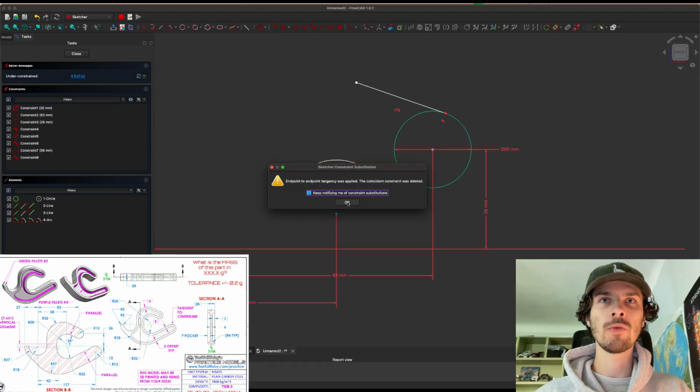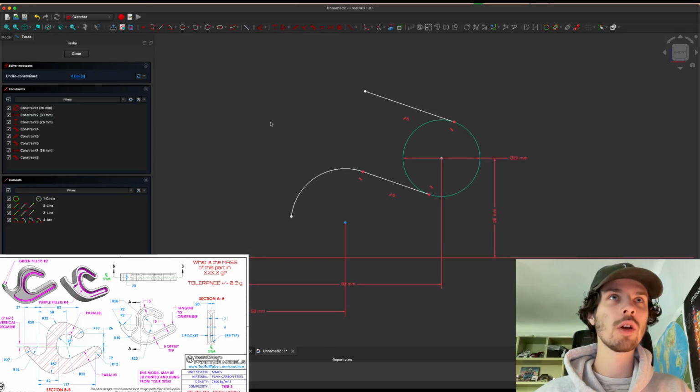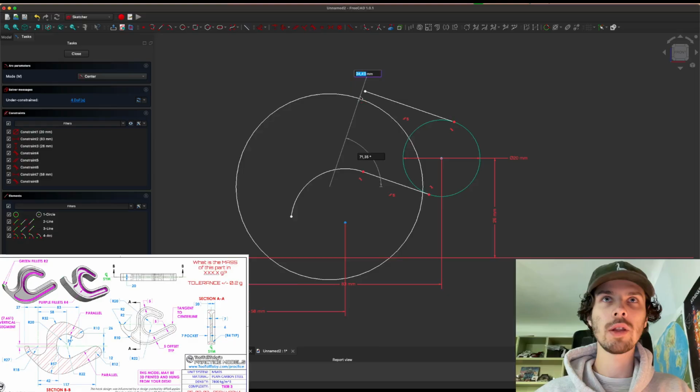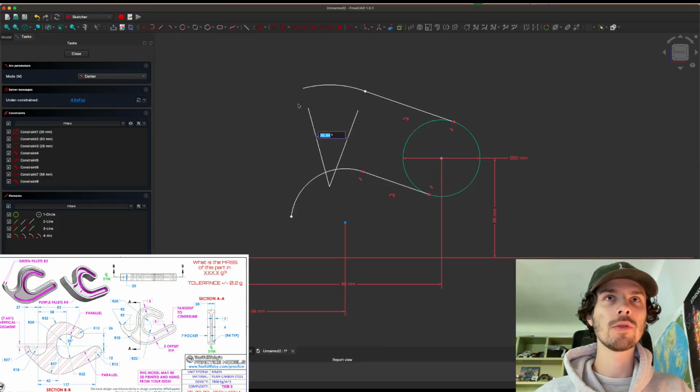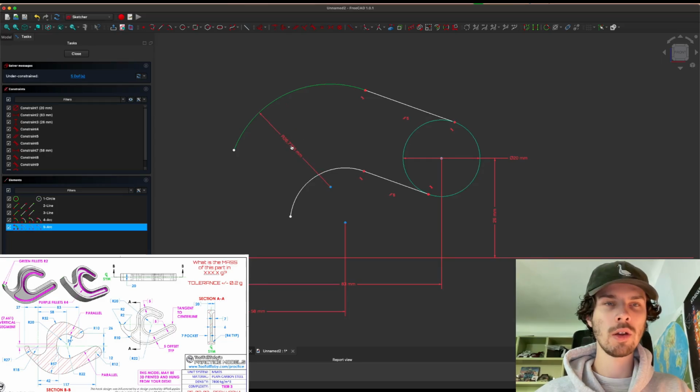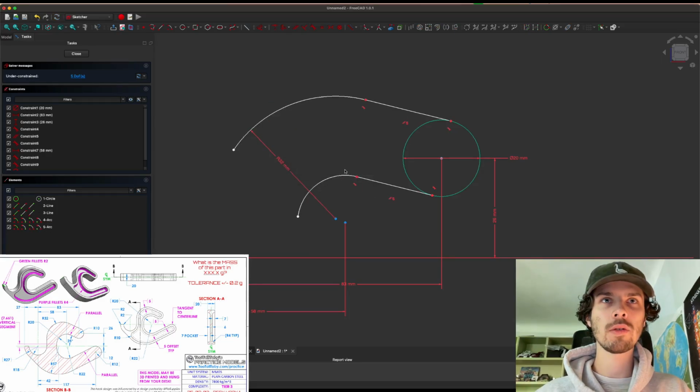I'm just gonna actually remove these messages because they're not errors, they're just messages saying a thing is happening. But yeah, so after that I'll add in the next piece. I'm currently using a 3-point tool, and adding the tangency. Adding dimensions to it, pressing D, clicking on the line, and we have 32 on that. Great. And we have 20 on this one. 20. Great.